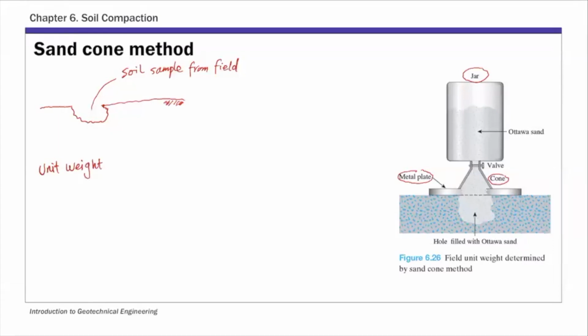we have discussed the different types of unit weight. You have the total unit weight, moist unit weight, dry unit weight. But basically, you have the same format, weight over volume. Okay. If it's a dry unit weight, it's weight of solids over total volume. If it's a moist unit weight, it's a total weight over total volume. Okay. So that's the definition of unit weight.